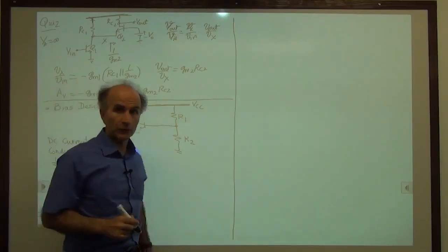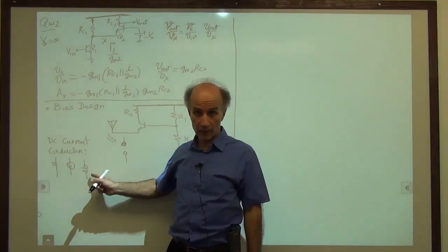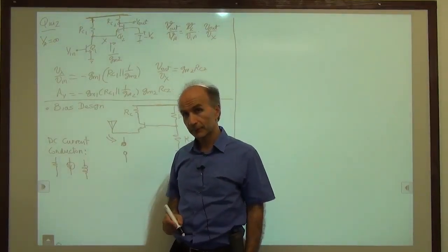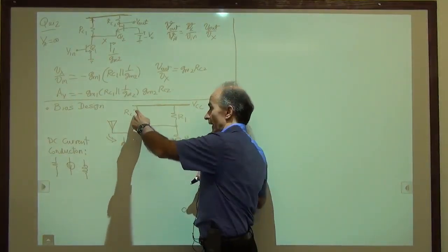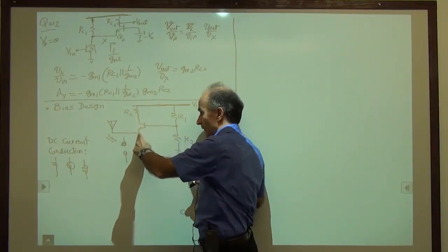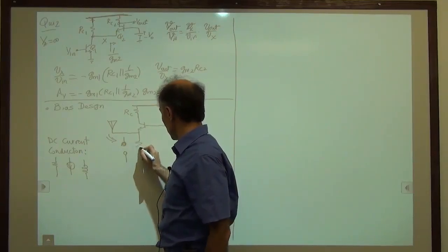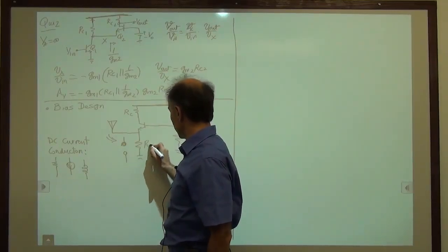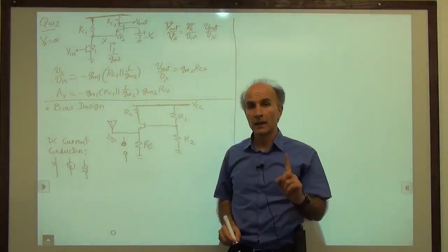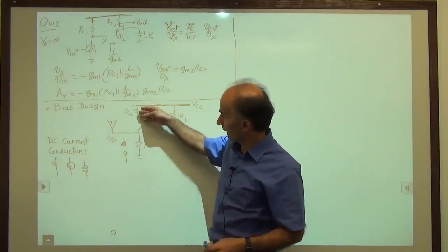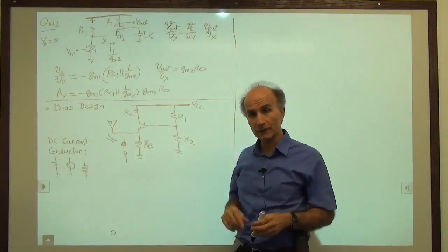In this course, we will try to use a resistor, a current source, but in more advanced courses, we can also try to use an inductor. Okay, so what this says is that in order to make sure that the bias current that starts from here can actually find its way to ground, we need to use one of these three. So let's go ahead and put a resistor here. I'm going to call it RE. So please understand that the sole purpose of RE is to allow the bias current of the transistor to flow to ground. That's it. Otherwise, we prefer not to have anything here.